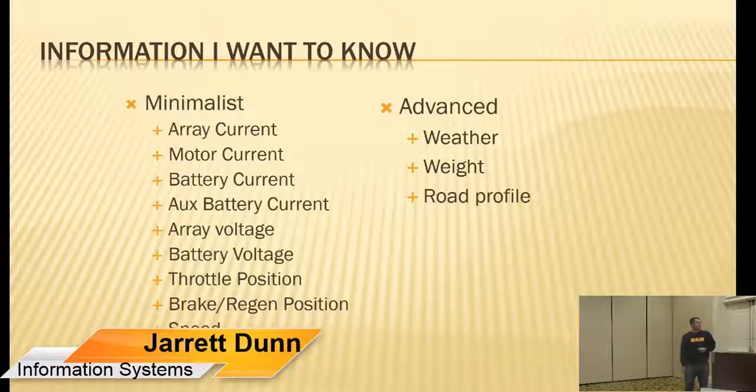So by measuring the throttle position and the brake position, you can go back and have a chart and show your drivers, like, you're really jumpy on the throttle. Person B is really smooth. This is how you should drive. It's good for providing feedback.